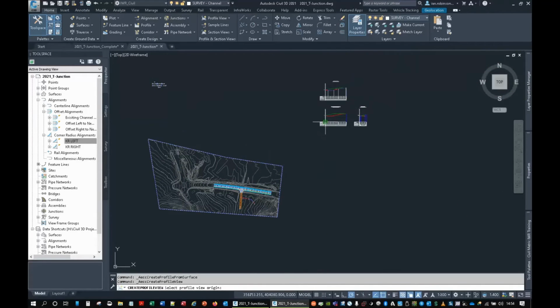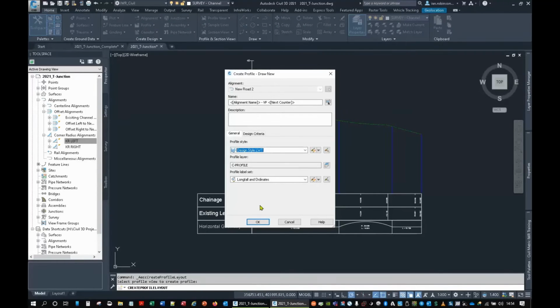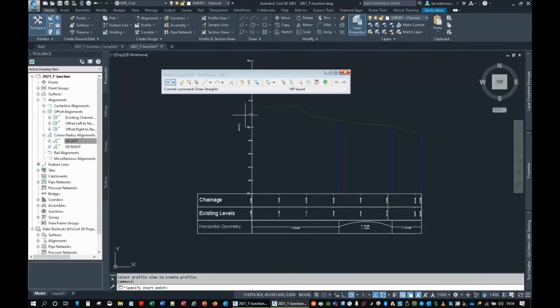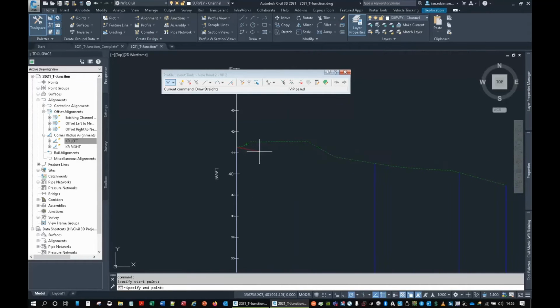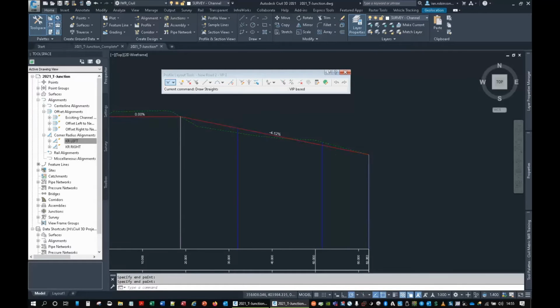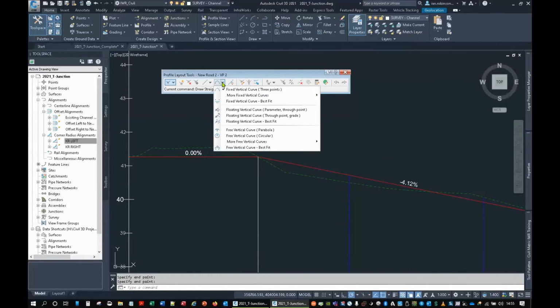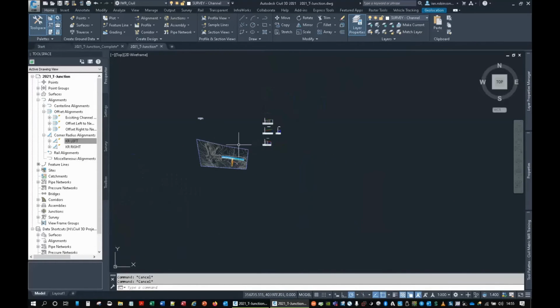So let's do road 2 now. So that's what that looks like, typical, going through a right big lump there. Profile creation tools, and okay. And again, just draw a straight to start with. Now I'm going to tie in here, I'm guessing that that won't be far out, I'm not sure. So I'm just going to pull it straight across here and then down to here. I'd like it fairly close to it, but we'll let the software worry about it, and then we'll come back to the profile at the end. And we'll deal with that at the end.